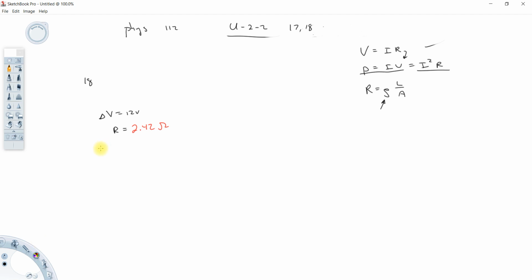I'd probably start, no doubt, with Ohm's law. Voltage equals current times resistance. And you can now calculate a current. And you can also calculate a power from current times voltage. By the way, check it against I squared R. You should get the same value. Now this power will come out in watts. That's what they're looking for in part A. Let's see, part B. How many minutes will it take to heat up some coffee?